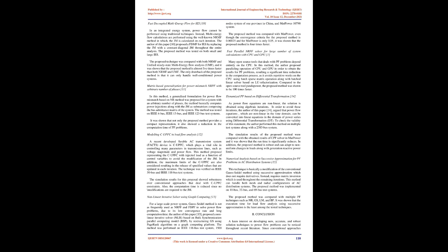The author argued that the conditioning of the bus admittance matrix has the tendency to be improved depending on the size of shunt admittances compared to one another within the system. The method was verified on multiple test systems along with the real grid networks in Italy.